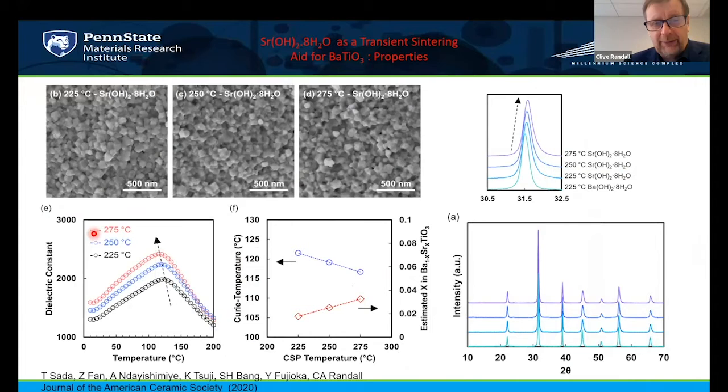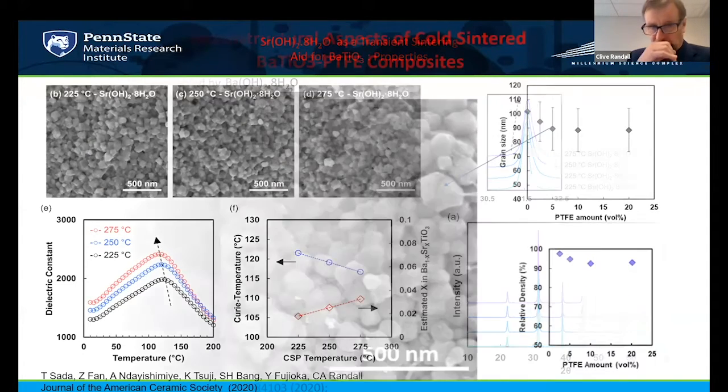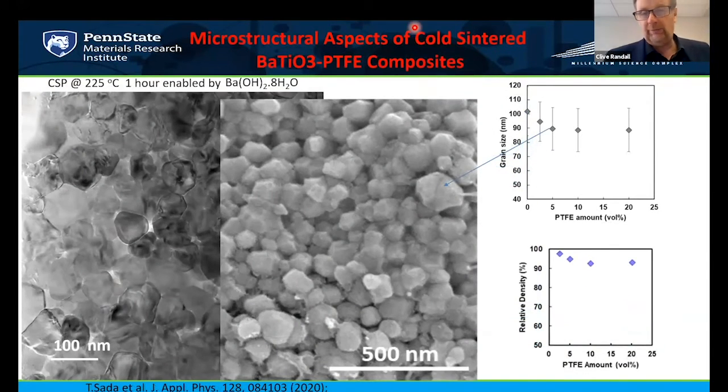And it's that type of technology that allows you to do solid solution, because you can then look within that family of material and dope barium titanate with strontium, for example. You can also add polymers now to barium titanate, but at very, very small volume fractions. So here you can see we're looking between 0 to 15 volume percent of polymer. And this is the type of microstructure.